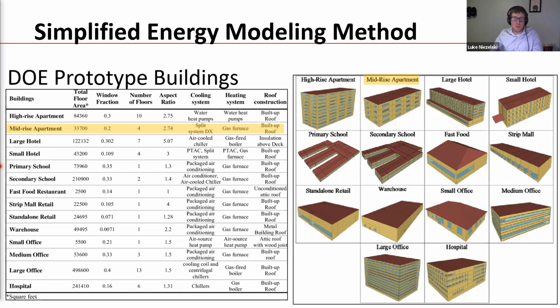We prefer a more passive option, which is to replace it with a high performance window that isn't going to see that condensation, or there are other creative ways to go about it, but we try to stay away from energy-using options like a radiant heating system. Sometimes that's the only option. So you have a historical building where you want to keep a steel framed window but you are having condensation issues.